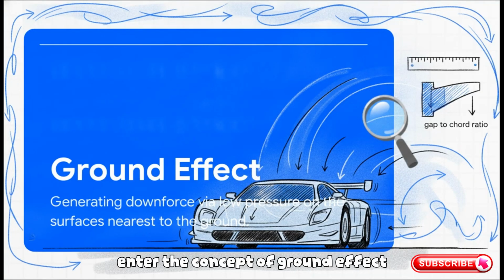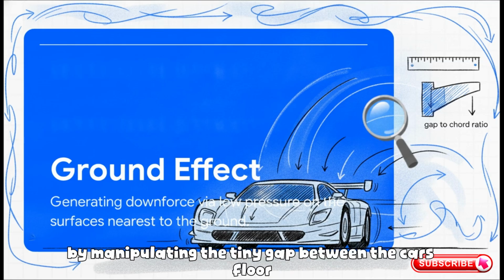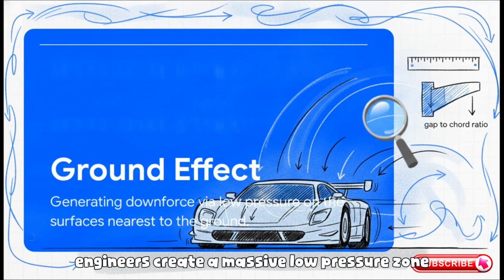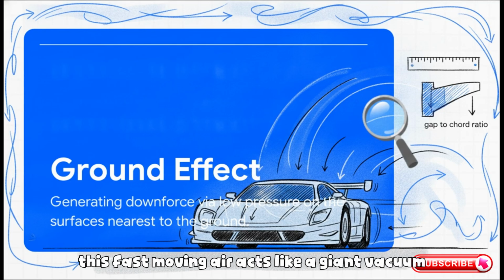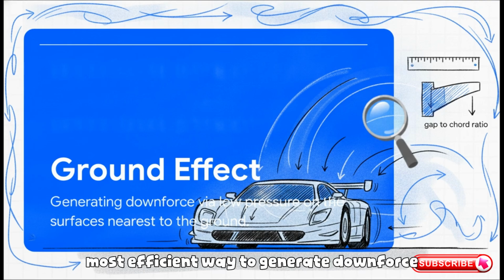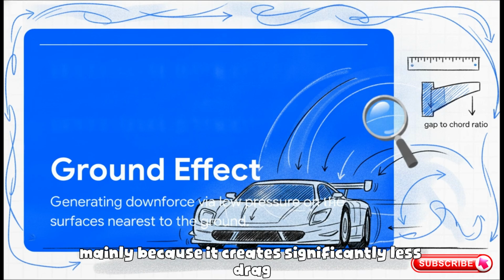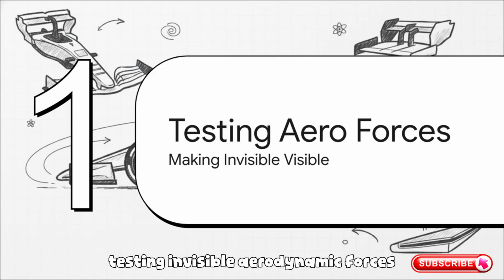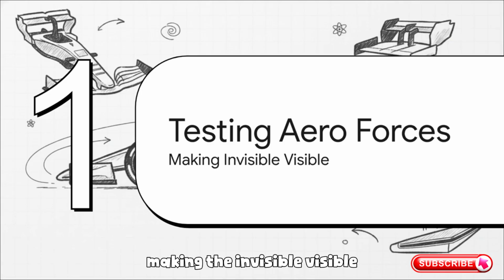Which brings us to Section 2, the physics of ground effect and how engineers manipulate airflow. Enter the concept of ground effect. A race car is essentially a giant low-flying inverted wing. By manipulating the tiny gap between the car's floor and the track, and we are talking about a gap sometimes measuring just millimeters, engineers create a massive low-pressure zone. This fast-moving air acts like a giant vacuum, literally sucking the chassis downward. It's the absolute most efficient way to generate downforce, mainly because it creates significantly less drag than those giant upper wings.